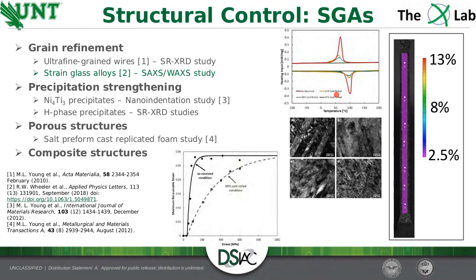And so we went to look at TEM here, and you can see you've got these larger twinning structures that, as we continue to load the material, we break those up. Eventually we get down to nanometer size twinning in the material, little regions where they can twin. What that ultimately leads to is, normally when you load the sample, you would see hot spots. All the loading would happen at one spot in the as-received material.